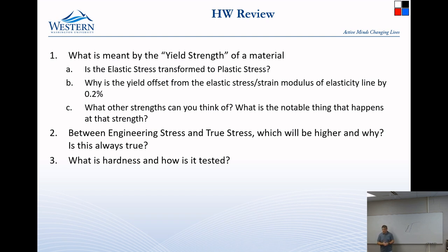So it comes from the engineering stress strain graph, and it's odd because it sort of exists and it kind of doesn't exist. It sort of exists because we're mismeasuring the part. Right? If we were doing a true stress strain graph, it just continues going on. There is no ultimate tensile strength that you can measure. But on an engineering stress strain graph, it gets to this point that's high, and the highest point, and then it starts to drop off.